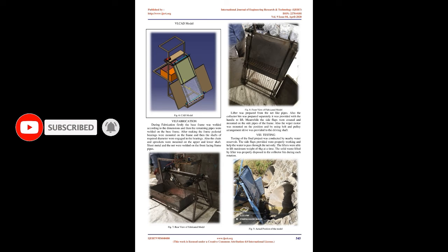Bearing. The shaft diameter is 20 mm. Therefore the ID of the bearing needs to be 20 mm. From the calculations we have decided to use RB204 pedestal bearing. Pedestal is nothing but the plummer block. It is used to provide support for the rotating shaft with the help of a compatible bearing. Chain and sprocket. We have used pintle chain and 6-inch sprocket, as per the standards available in the market satisfying our requirement.